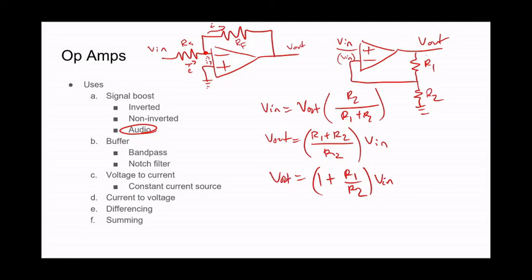It's a little simpler to think about, which is one of the reasons why I like it. And it doesn't invert it, which is also good. And it gives you this plus 1 as a little bonus there for you. So this is a great tool. Both of these are really good tools for boosting a signal. Whether that's a small audio signal, or something coming off of some kind of measurement device like maybe a strain gauge or something else like that. You want to be able to amplify that to something you can measure. This is a perfect way to do it.